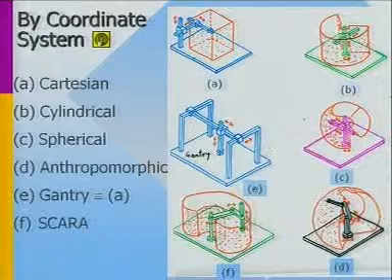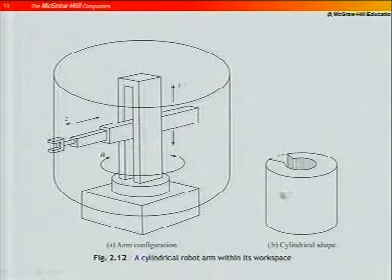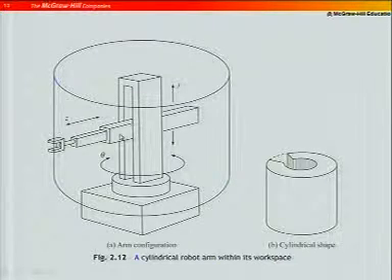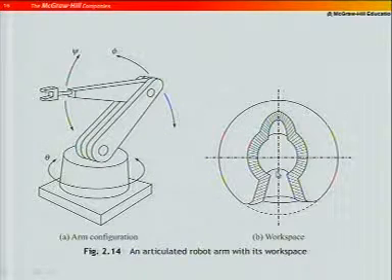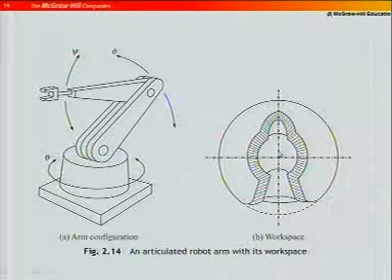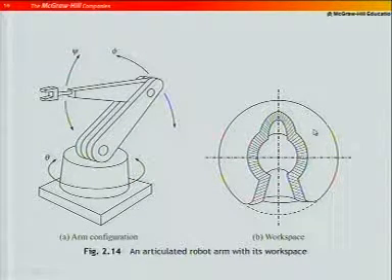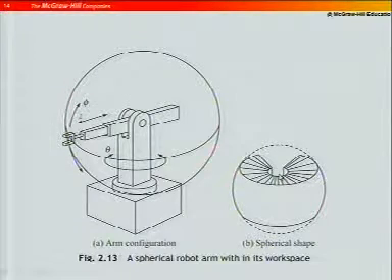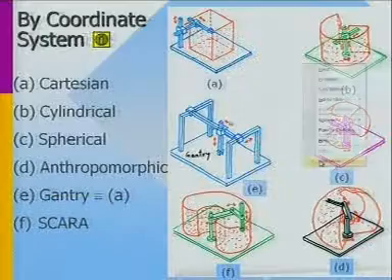Here you can see the cylindrical, this portion is hollow, because the end effector cannot go to the extreme positions. The same here, it is hollow here, and here it is not very clear, but some portions will be hollow. It will not be hollow at the center, it can have hollowness inside also. So, an articulated robot can have hollow regions in places other than the center, whereas the spherical and cylindrical have hollow only at the central zone. Okay. Next.